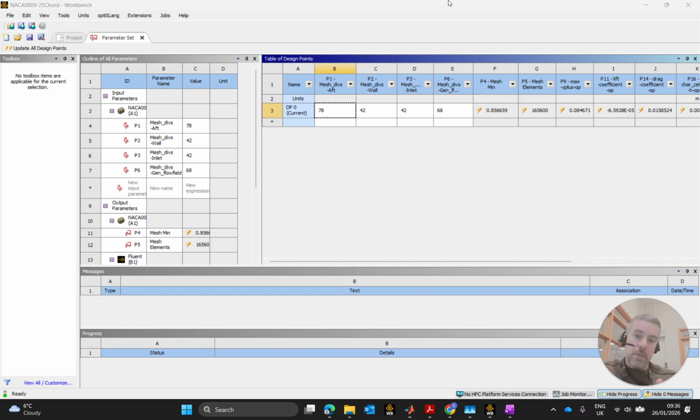It just says that the mesh, the discretization, the turbulence modeling and our numerical method for solving this physical scenario is good or bad, regardless of what that physical scenario is. If we bring new physics into it by refining even more, we might have to alter what we do with our mesh to capture that adequately.